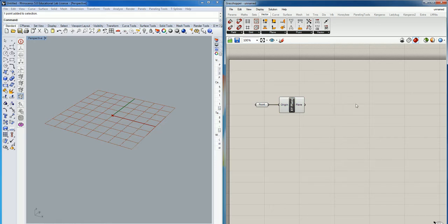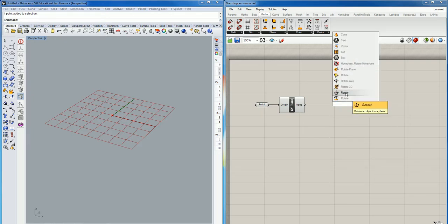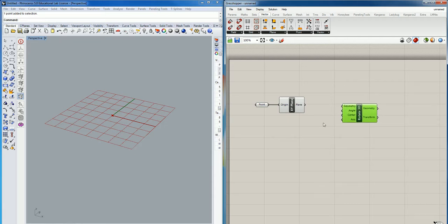And so the component that you guys needed to use to get the angle of declination was Rotate 3D. So the goal of it was to feed in this geometry and then figure out which axes to rotate on and how far to rotate. So for example, if I hover over the axes command, it has one locally defined value, and that value is 0, 0, 1. So what axis does that define? It defines the z-axis, right?